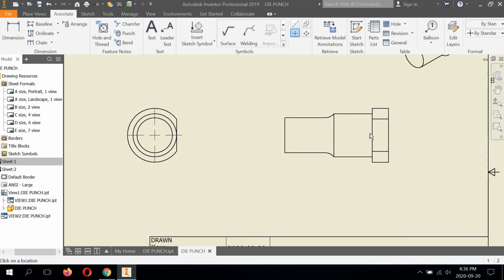We're also going to create one for the right side view. Now, the center line should pass through anything cylindrical to ensure the operator that we're working with a round object, right? Because this doesn't look necessarily round from the right side view. It looks more like a block. So we're going to select center line, which is above, and we're going to select the center.